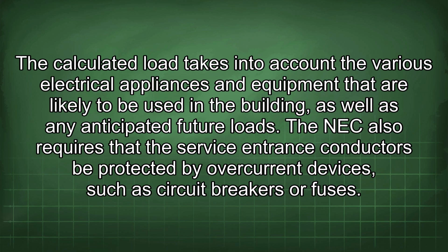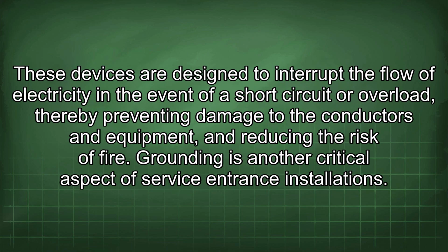The NEC also requires that the service entrance conductors be protected by overcurrent devices, such as circuit breakers or fuses. These devices are designed to interrupt the flow of electricity in the event of a short circuit or overload, thereby preventing damage to the conductors and equipment and reducing the risk of fire.